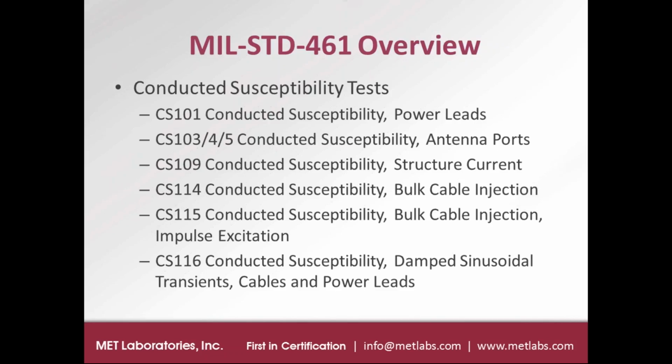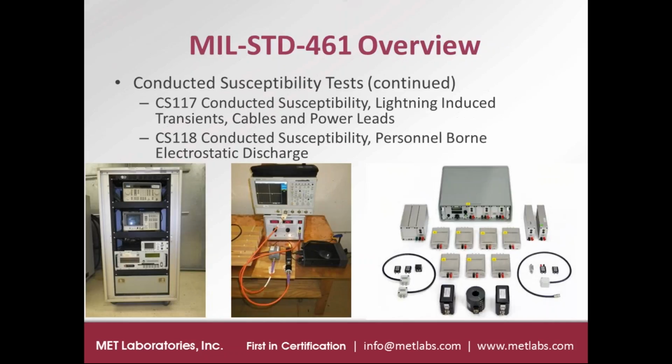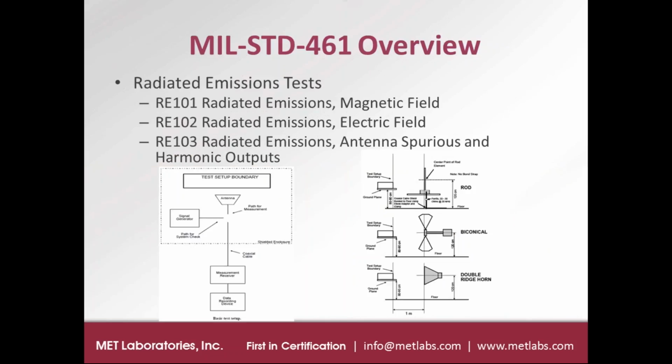And the last two conducted susceptibility tests are CS117, which is lightning-induced transient susceptibility, and CS118, which is personnel-borne electrostatic discharge. These two tests were added to MIL Standard 461 version G, and I'm going to talk about them a little bit more in a couple slides.